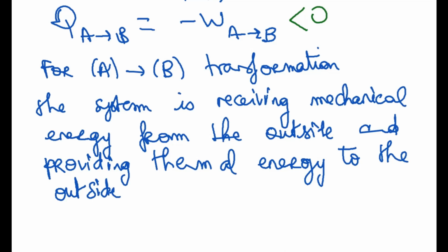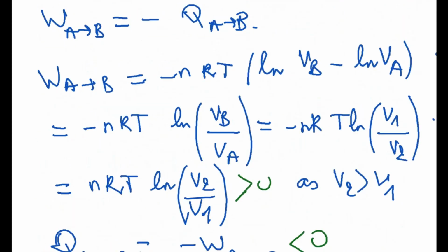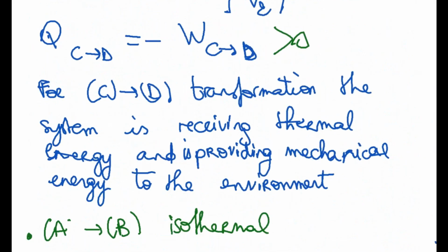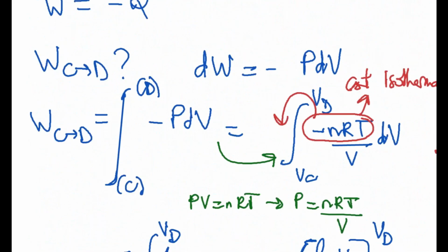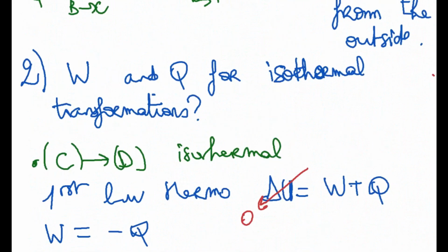Okay, so now that we have this information, my advice is to come back to the Clapeyron diagram before even making the calculation of the efficiency. The next step is to make the calculation of the efficiency, but I recommend you come back first to the Clapeyron diagram and represent the information that you just got in terms of what is positive and what is negative for the heat and the work. Why is doing this important? Because when you calculate your efficiency, this is going to help you see things better in terms of what is the benefit and what is the thing that the operator provided before.